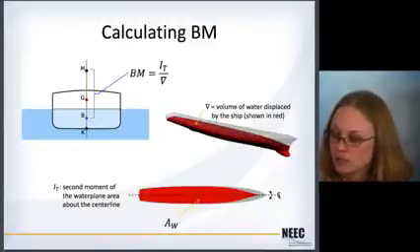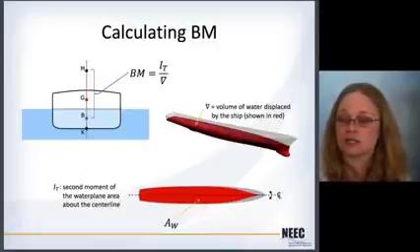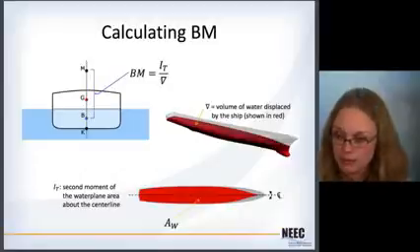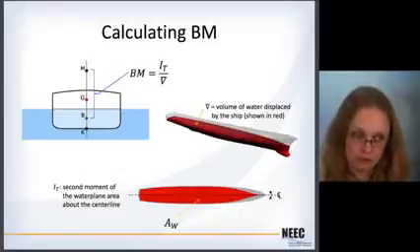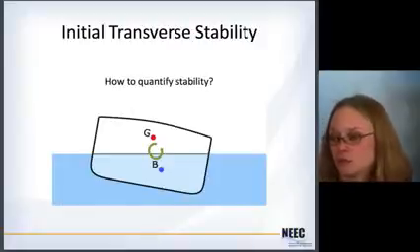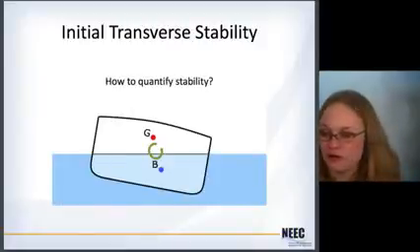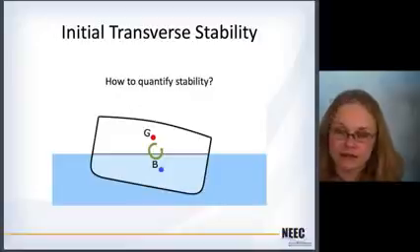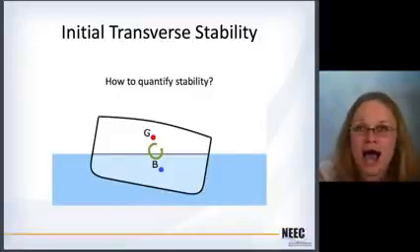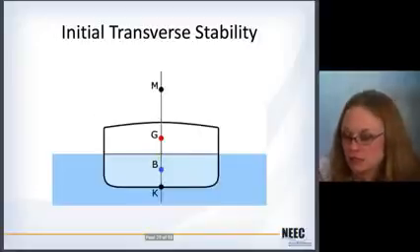So you see here, this is what it is. Those numbers you get out of your hydrostatics program, it will also calculate BM for you. So you get a bunch of BM values for different drafts. Okay. So really what we're trying to get after here is we're trying to figure out a way to quantify stability, right? Our little examples where we're pushing down on blocks are all well and good for the concepts, but we've got to put a number on this stuff.